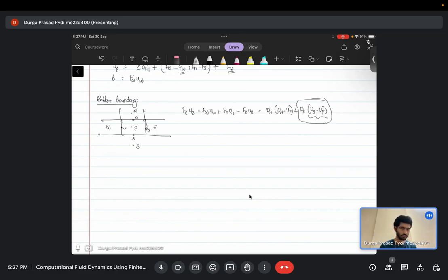Like we do in our Dirichlet condition, whenever we have a Dirichlet condition, what we were doing previously is, when you have your gradient term, this is your gradient term del u del y on the south face times area, here area is delta x. So what we were doing previously is mu times delta x by delta y times up minus us, but this particular formulation is not possible in this scenario because we have a boundary here. So how do we replace this? Same as we did previously in conduction, we just take the half cell, so delta y will be replaced by delta y by 2, and then you have up minus u south boundary.